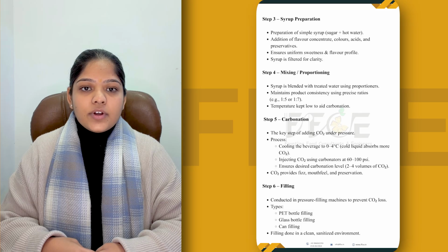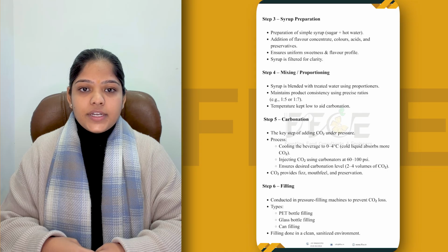Now we'll move forward to the fifth step, which is carbonation, the most critical step. The beverage is cooled to around 0 to 4 degrees Celsius because cold liquid absorbs more CO2. Carbon dioxide is injected under pressure using a carbonator, typically between 60 to 100 psi, achieving the desired carbonation level. CO2 not only gives fizz but also enhances mouthfeel and helps in preservation.